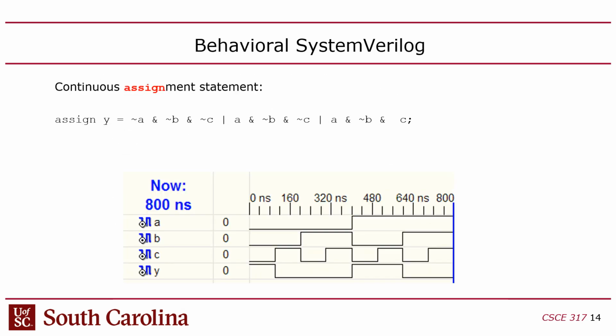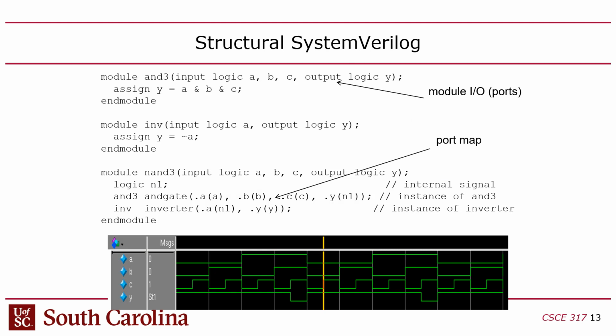Okay, all right, and then you guys remember from 611 we use a waveform-based debugging tool for this. I'm going to cover Signal Tap too, because I think it's going to be needed for lab 3. So this is from a simulator, but like I said, Signal Tap is a JTAG-based tool that allows you to actually get these kinds of waveforms from signals that are actually on the FPGA. Right? So the way it works is the Signal Tap probe is a RAM, and it has a trigger condition. An oscilloscope has a trigger too.